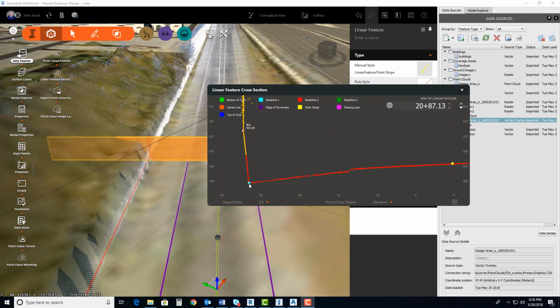what I did was carry the bottom elevation of the wall through with that same break line 1, and then I used the top of the wall here where the fence starts, and I just went ahead and carried that break line 2 through with that. Now, you could have done this any way you wanted. You could have stopped at the jersey barrier where it stopped completely and started a new break line, or you could carry it through like I did here in the demonstration. It's totally up to you. You have that leeway of being able to do that.